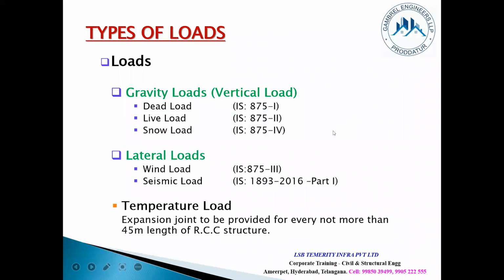Next thing is we have to focus on the load calculations. We have different loads like dead load, live load, wind load, seismic loads. For this session and this particular webinar, a short session, we are considering only gravity loads like dead loads and live loads. So there are codal provisions.